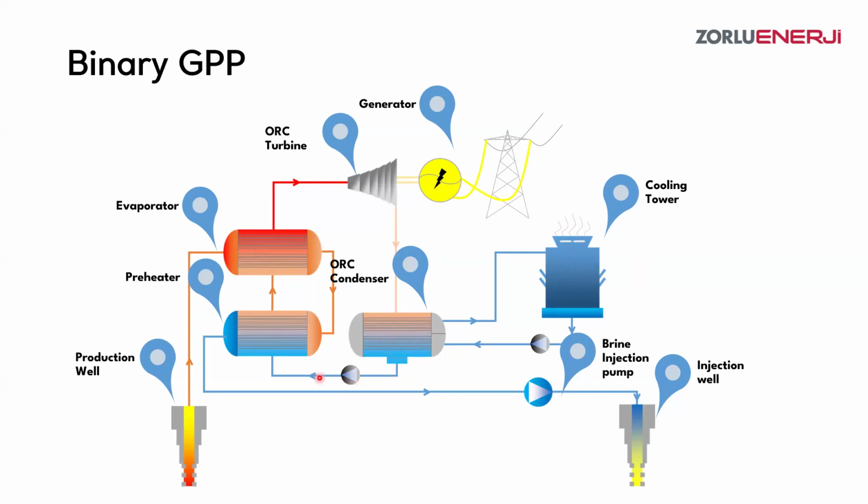Afterwards, you are sending that to a new piece of equipment, which is called a preheater. Again, the preheater is a heat exchanger, which is, by the way, different from the evaporator just by this: it is not changing the phase of that liquid. It heats it up to the point that it could boil with a little input of heat. By dividing into two stages, you are using this geothermal fluid afterwards in the preheater, creating additional efficiency in here, okay?